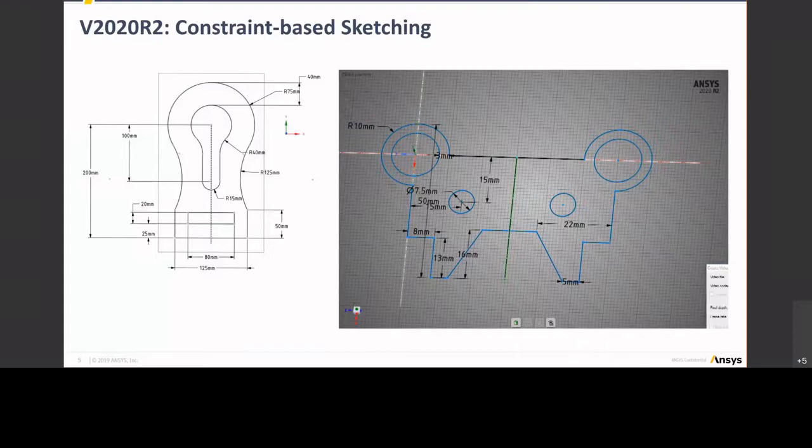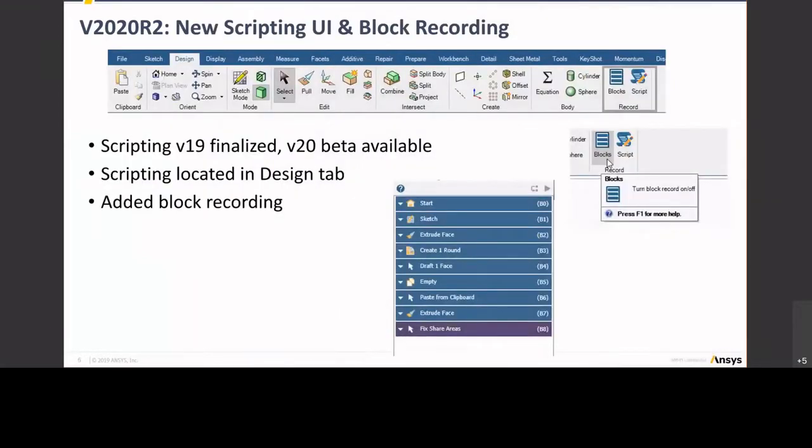And if Tim presses the next button, the idea is that in combination with this block recording functionality, which you can activate from the Design tab, you can switch on block recording. And if you do that prior to setting up that constrained sketch, as per the example just there, it basically records all the dimensions and allows you to modify those dimensions, such that if you then convert this into 3D, you have really a defining underlying 2D sketch that parameterizes and exposes the dimensions that you may want to change and update to 3D design.